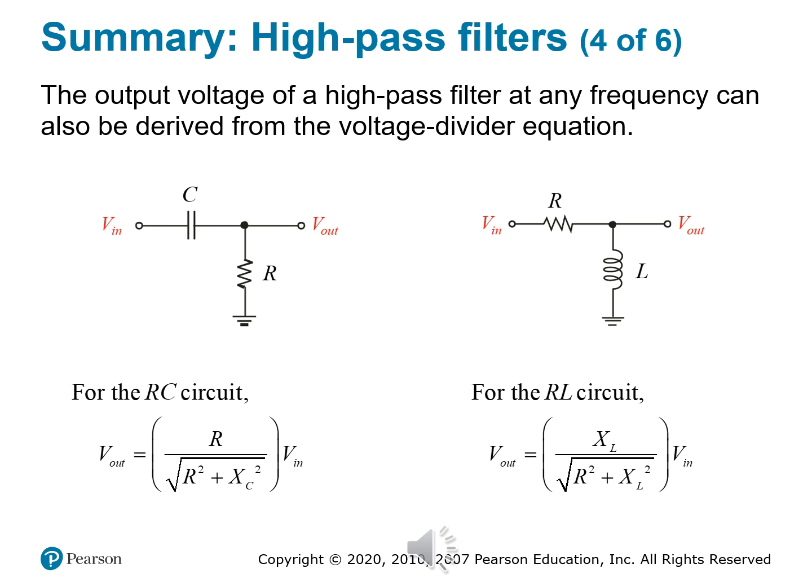If you look at it, it's directly proportional to frequency. So this inductive reactance increases with frequency. At low frequencies, X sub L is tiny, so you have a low output. But as the frequency climbs, X sub L dominates, and you have a high output.